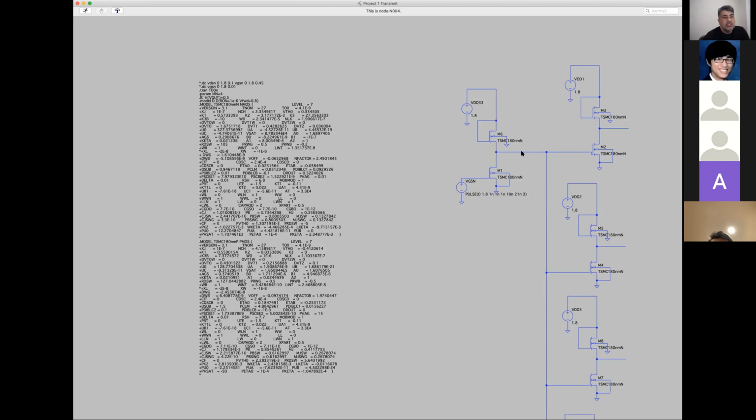You'll see a voltage high-low going pulse that will be inverted with respect to this input voltage pulse. Given the nature of the circuit, it'll probably be a lot smaller, maybe a volt swing sort of centered around 0, depending on your circuit. From there you can calculate your delays, rise time, fall time, etc. Does that help?